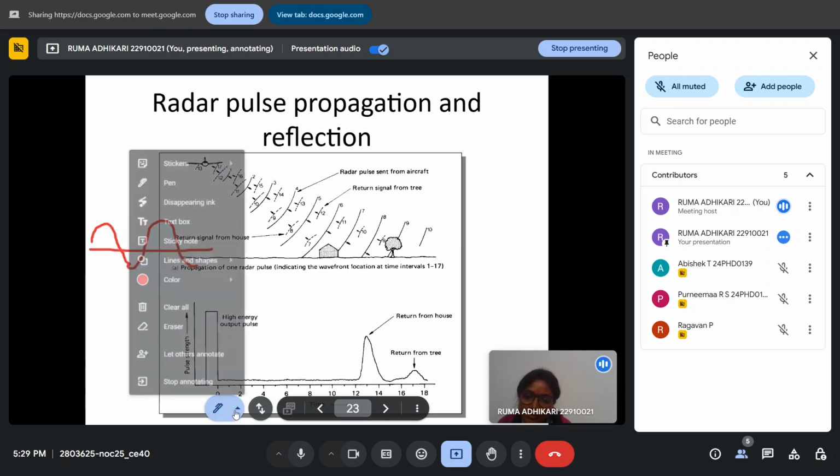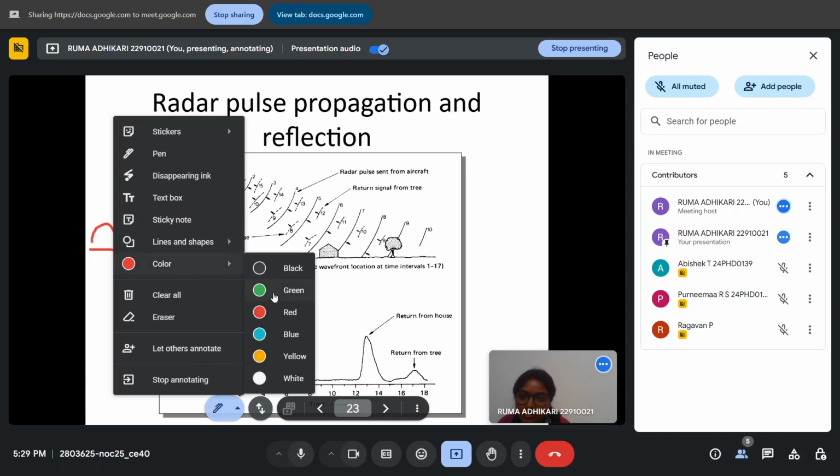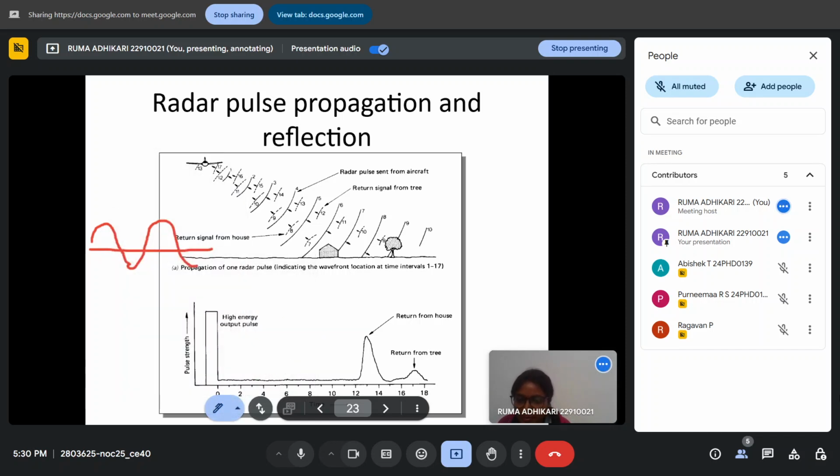This is the transmitted signal. Then the received signal will have some phase shift, because in that time the sensor moved, so it will be shifted a little bit. The received signal will be somewhere like that, it will not match. It will have different peaks and different shapes, both are not the same, and it will be shifted in this direction.